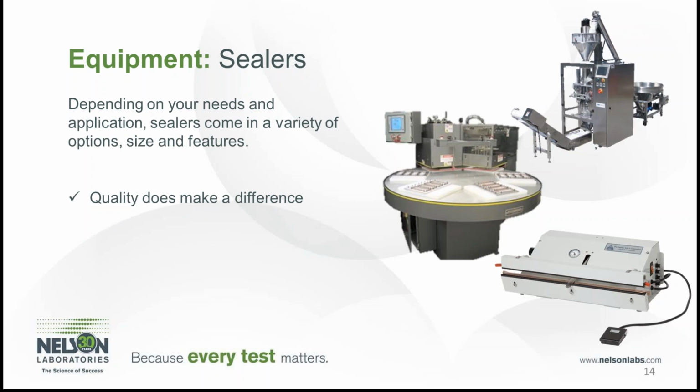Over the past year or two, we've seen several instances where low-quality sealers were used and implemented in the packaging system, and the packages themselves failed integrity and strength testing because the sealers were unable to maintain a consistent seal across the entire package because of temperature, dwell, or pressure fluctuations, or the inability for the sealer to recover quickly enough to get to subsequent samples.